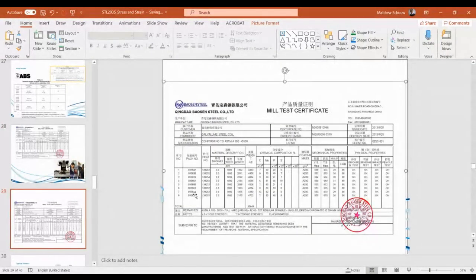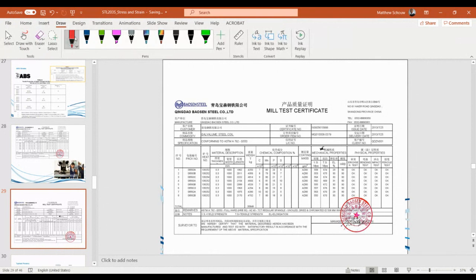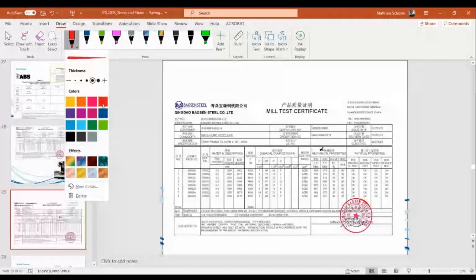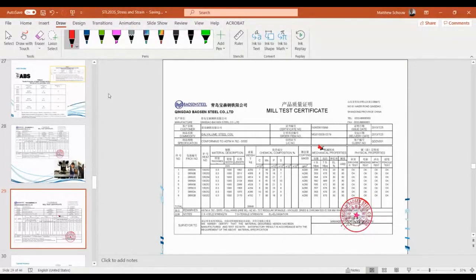And as you can see there, it'll tell you it is of a specific coil and is rolled, and tells the length of the plate and the width and all of that, and the chemical composition. So this gets tested at the mill. And then over here, you guys see, it's the mechanical properties. So we have your yield stress, your tensile stress, your elongation, and HRB is a hardness test. These properties must conform to that ABS standard.